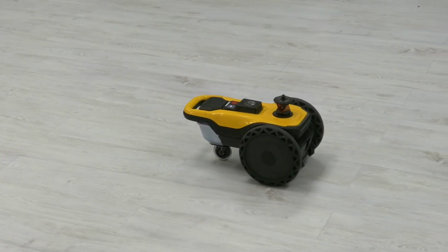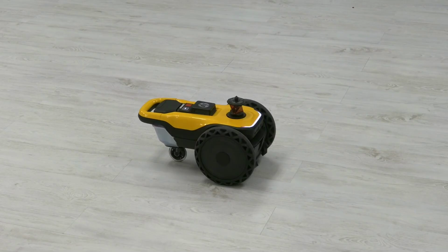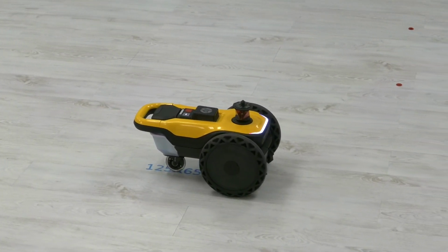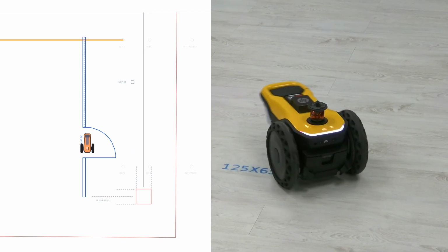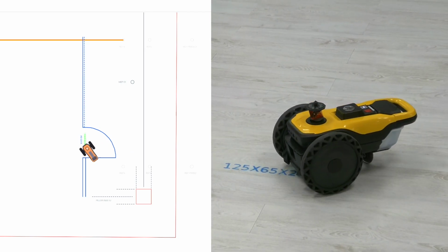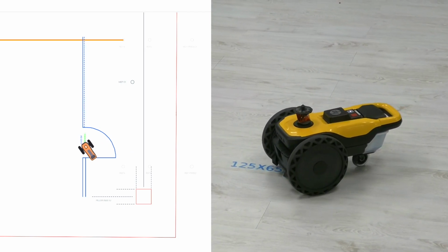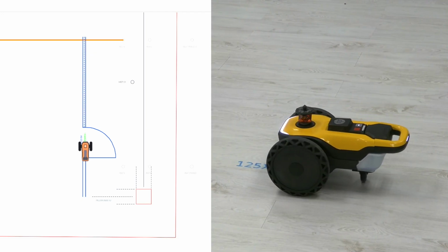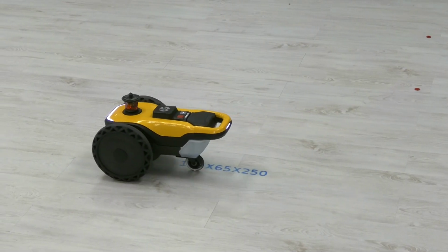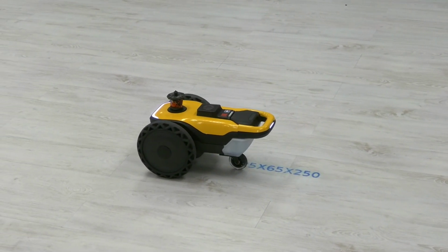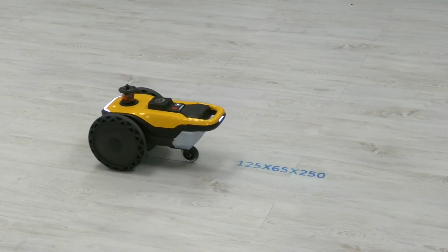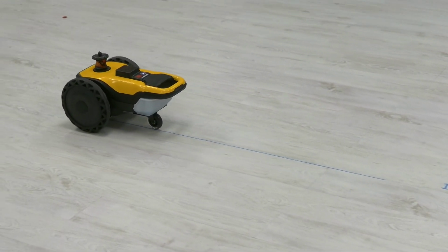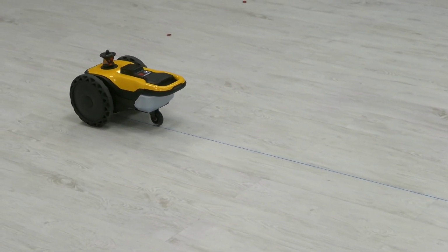As you can see in the user interface, there is a real-time representation of SitePrint's moves. The elements that will be printed are displayed in blue. The blinking segment is the one that is going to be printed next. And once it has been printed, it will be displayed in green. If by any chance a line cannot be completed, for example, due to an unexpected obstacle, it will be displayed in yellow for you to know that you will have to go back to this segment. This way you can keep track of what has been printed and what has not.